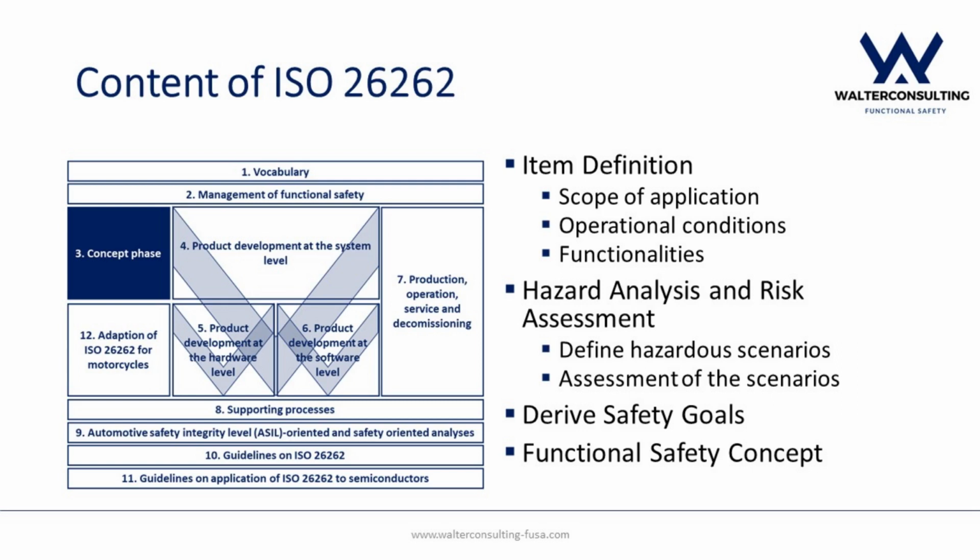Another point defined in this chapter is safety goals. Safety goals are top-level requirements derived from the hazard analysis and risk assessment. They are the base for creation of the functional safety concept. The functional safety concept describes mechanisms for error detection and error handling.